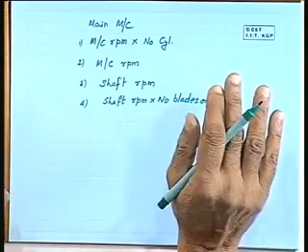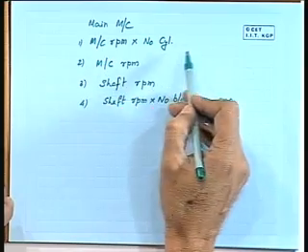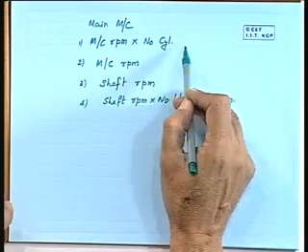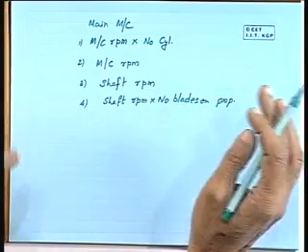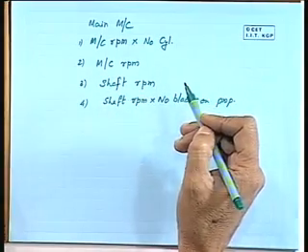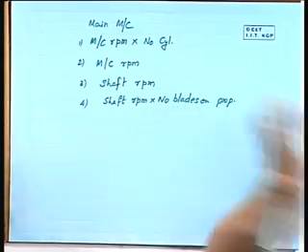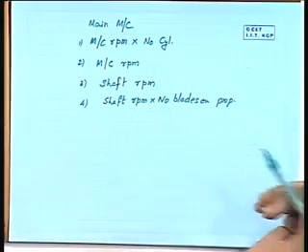In a similar fashion, the genset will also generate similar frequencies, that is, the prime mover: number of cylinders multiplied by RPM, then the RPM, then again it may have a gearbox, and then you have the generator shaft RPM.